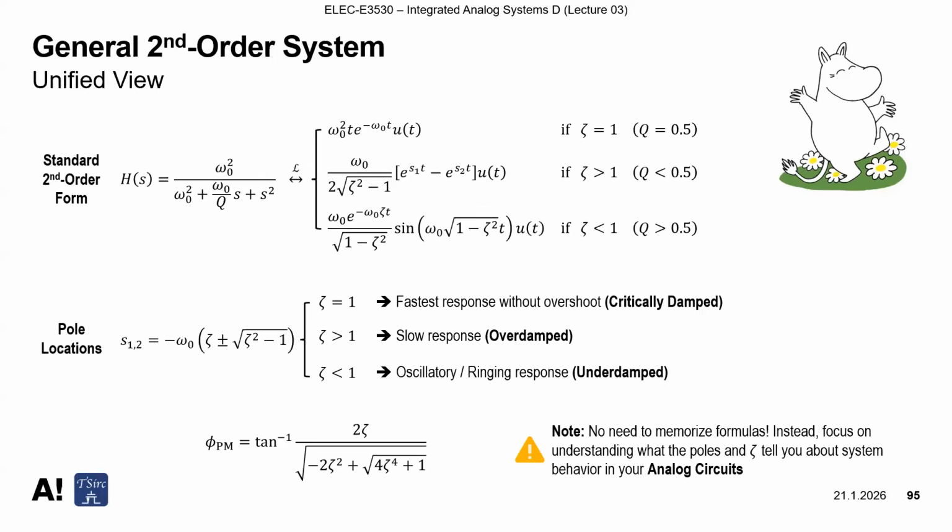Is it related to this? If you are talking about the Miller compensated amplifier, the phase margin was too high. That's why I couldn't make the speed, the slew rate, better.